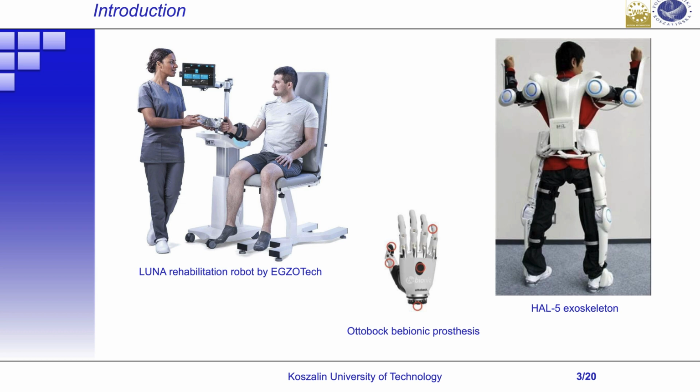EMG signals are widely used in today's technology. They are successfully used to diagnose and treat some neurological disorders. Considering the low voltage range, very high requirements are placed on the measuring apparatus to determine the sEMG signal level as accurately as possible. Advanced measurement probes with implemented preamplifiers that amplify the signal already at the muscle are available